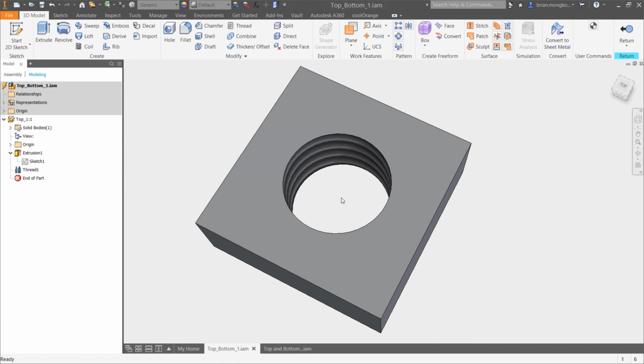But if you have all modeled threads and you have 1,000 threads in your model, then it will probably slow down your machine. Not just probably, that's certainly slow down your machine, right? Because each of those threads is going to consist of X many faces and edges and so on and so forth, right? It's not going to grab all of that as one face.